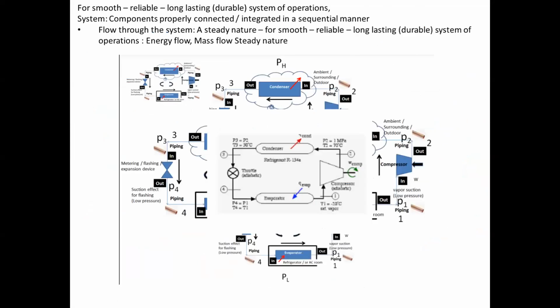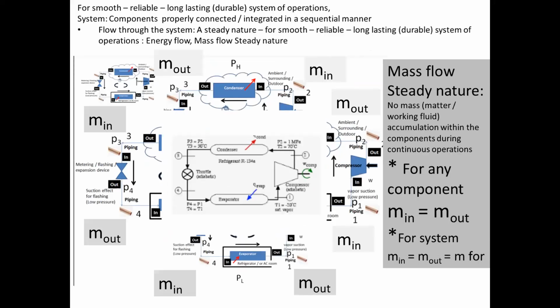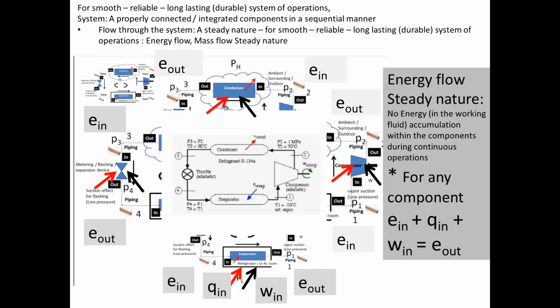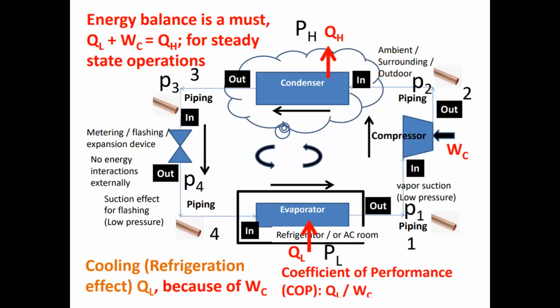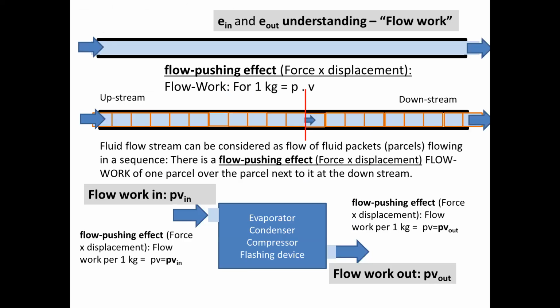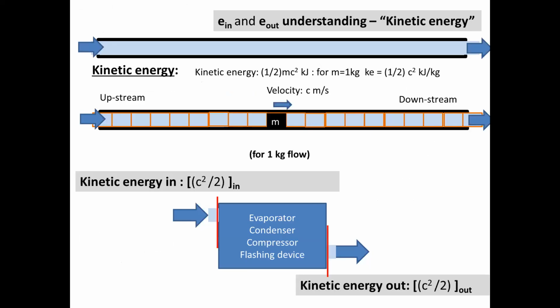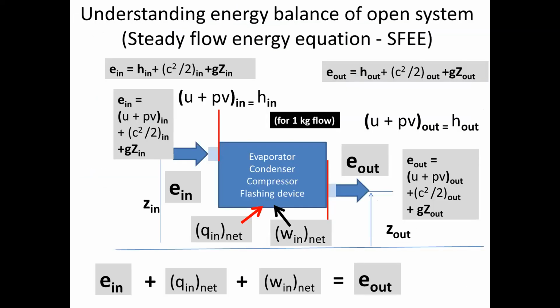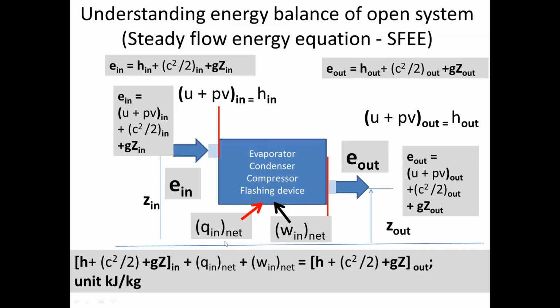No, sir. Oh, no. So hope you read this and you have some understanding about these energy interactions in flow processes. So whatever the component, evaporators, condensers, compressors, flashing devices, if you have a single input and single output, with heat and work interactions, you can write this energy balance.